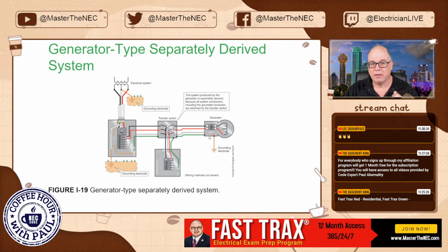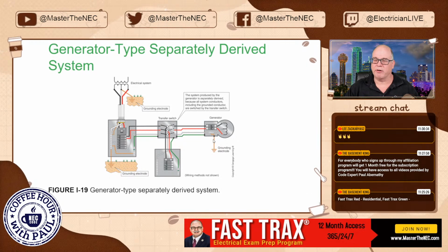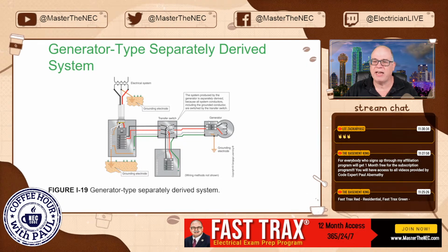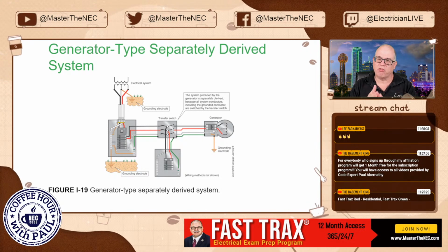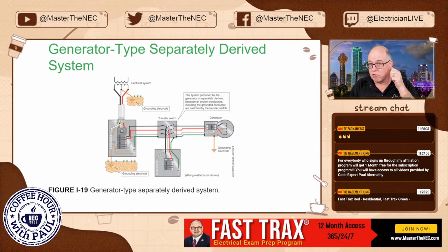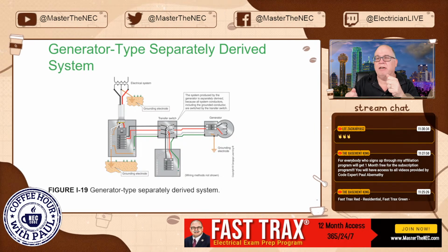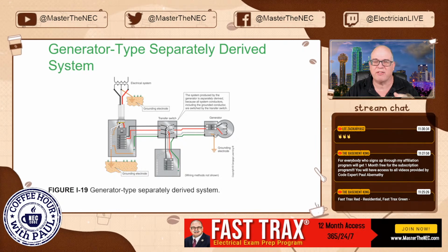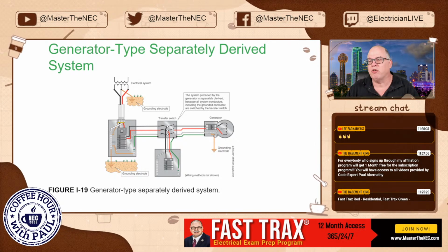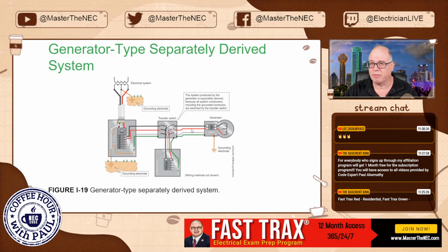Okay? So make sure, as an electrician, if you're installing a generator, that before you connect any of the conductors going out to it, the feeders going out to it, you check between the grounded point and the case and make sure it doesn't ring out. That's before you get any back feeding through these conductors. Just check it first and make sure you don't have a system bonding jumper installed if it's not separately derived.